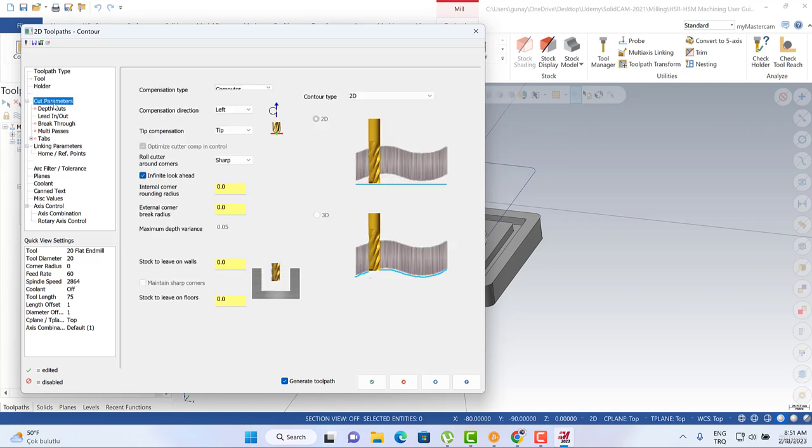And then we can turn to the cut parameters. When we turn to the cut parameters, actually, we're going to see the compensation type. Compensation type can be seen computer, control, and wear and reverse wear can be seen here. When you select the computer, actually, your tool diameter is calculated automatically. So it means that you don't need to write any D offset in your CNC.